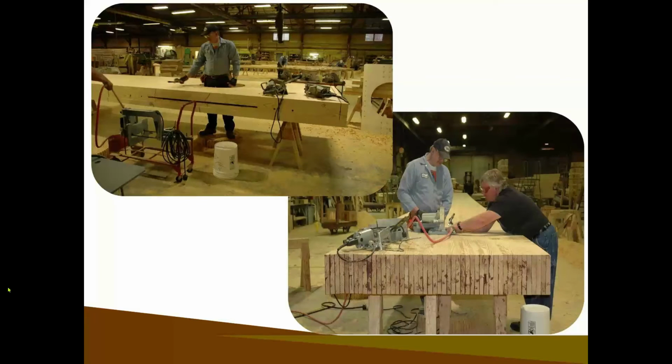And some other things, I know Bob was talking about holes in Glulam, which is great to have standards, but sometimes we can get pretty nuts with the fabrication. This here is a beam that has had to accommodate a 24-inch diameter HVAC duct. So we were able to taper the beam wide enough at one end to compensate for that loss of material. You can get really custom, you can really get around a lot of design issues.